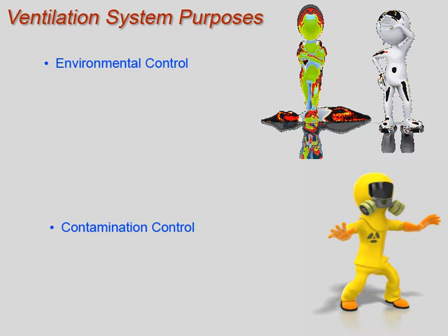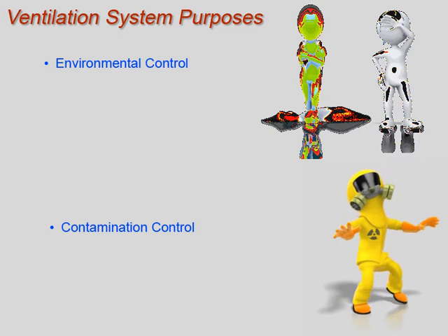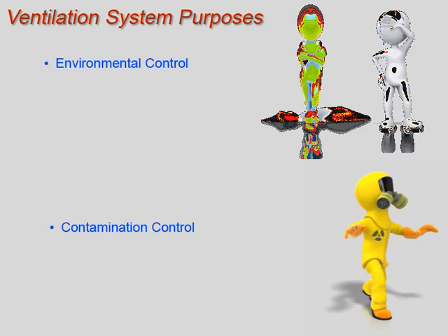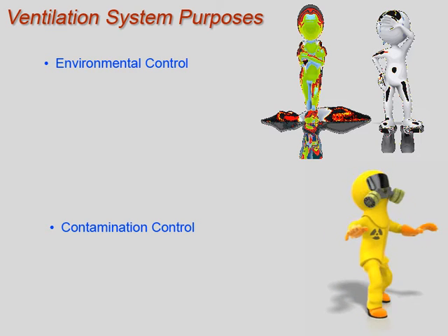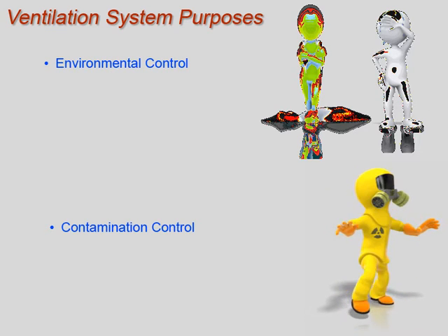Flow control is also used to ensure areas remain clean. All the air from potentially contaminated areas passes through filters prior to being released. This airflow is also monitored for radiation to ensure proper filtration.